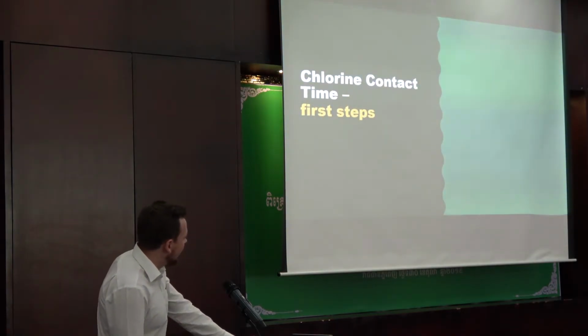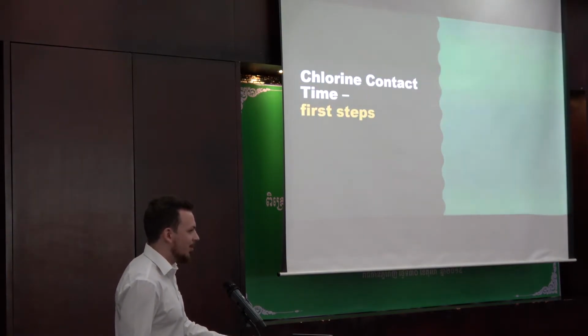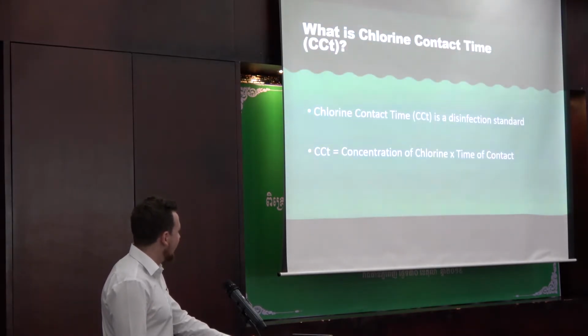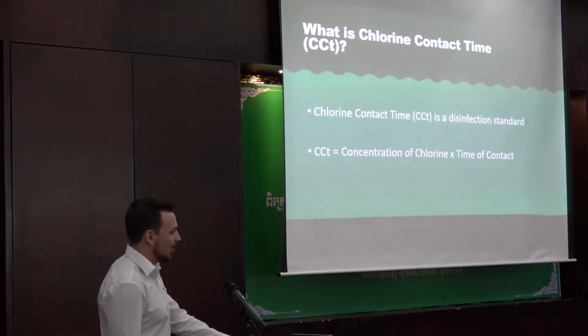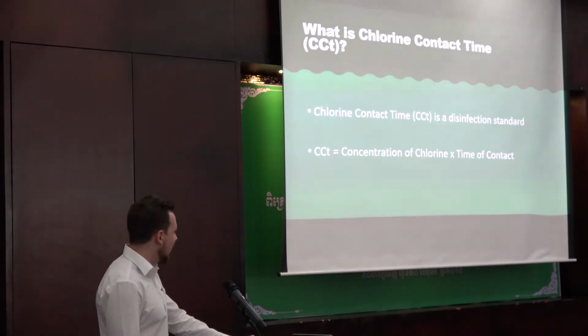We also began discussions on chlorine contact time. When the crews came out a few months ago, we had a chat with Melbourne Water at Tarago Reservoir, and we realised that understanding of chlorine contact time as a treatment process was very much in development. For those that don't know, chlorine contact time is a disinfection standard that's used in Australia.